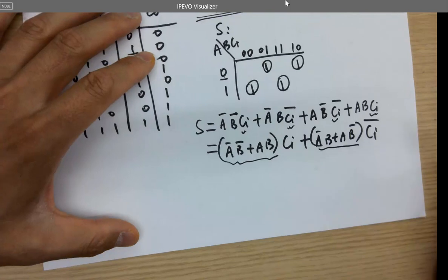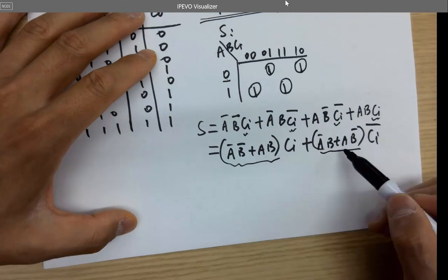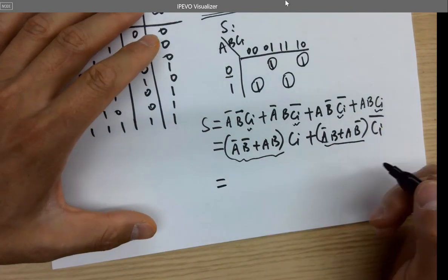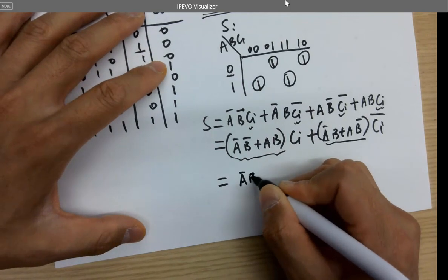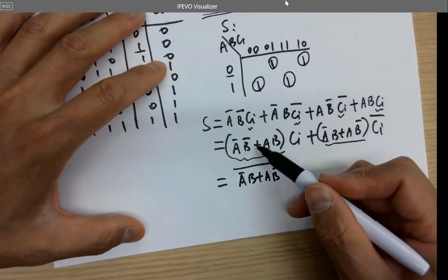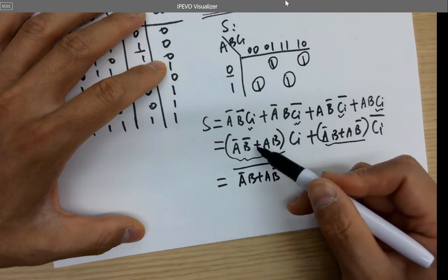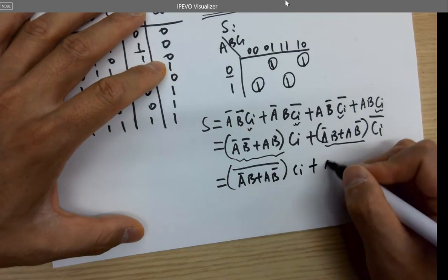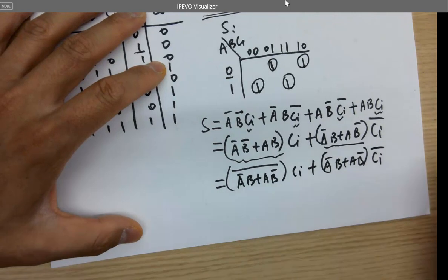And we derived on Wednesday that the XNOR is the inverse of XOR, vice versa, right? So let's just use XOR for example, and this is XNOR. So this becomes A naught B or A B naught, which is XOR, and this is the inverse of this, which is XNOR. Then CI or A naught B or A B naught, CI naught.